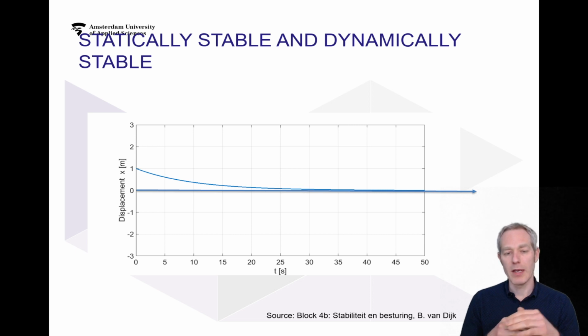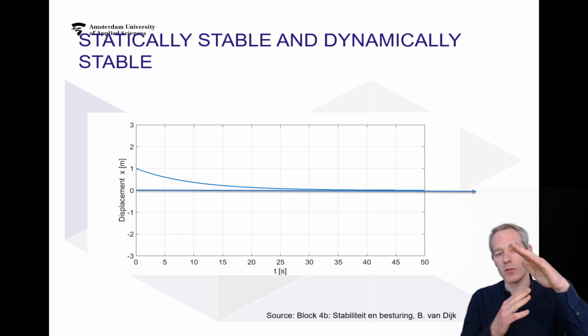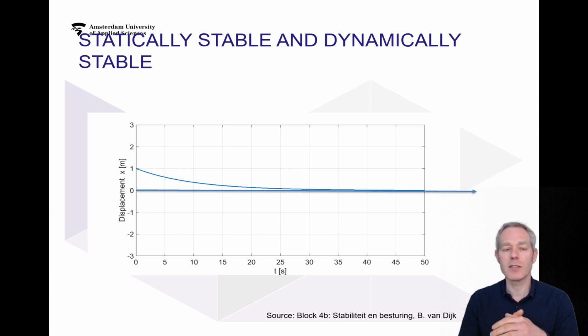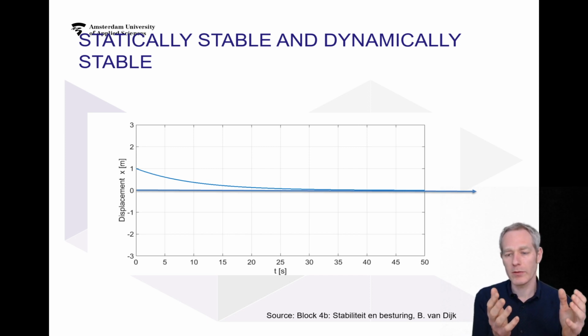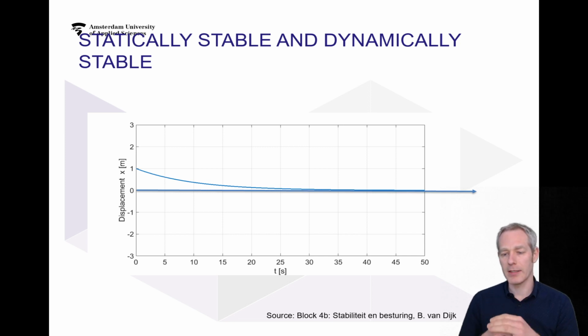But of course, if we have an aircraft which is pushed up, it will just continue to go up, but the tendency will be to return to its equilibrium position if it is a stable system. So there we have the distinction between stability, which we talk about typically in aviation, and stability, which we typically talk about in control systems.